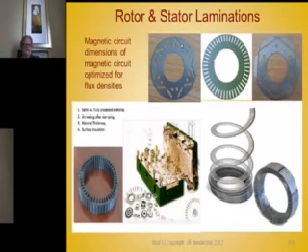And this is an IPM also, but here you have a slab magnet that goes that way with almost no reluctance component of torque. There's no soft salient pole in between the magnets. And in this example here, they wanted to put this soft iron in between the magnets to give this thing saliency, to get a reluctance torque component. So to get the same magnet area, you make the magnet in two pieces and put it in a V, and that's what that looks like.